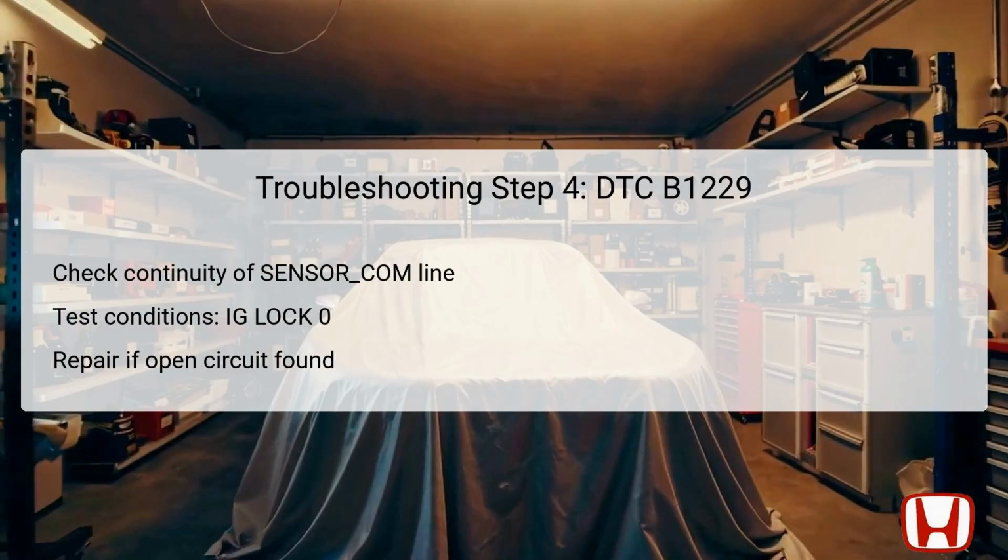Check continuity between test point 1 at the climate control unit, 32P connector, number 20, red wire, and test point 2 at the sunlight sensor, 5P connector, number 4, red wire. If continuity is confirmed, it signifies that the sensor COM wire is functioning properly.